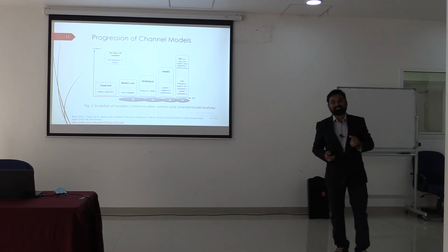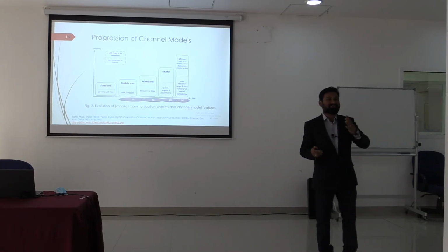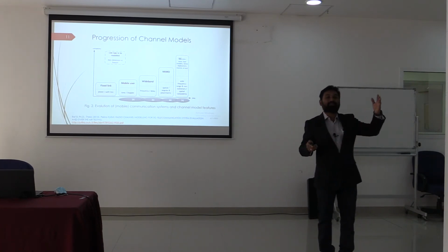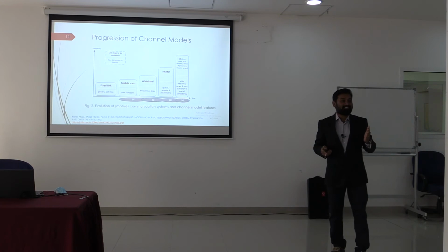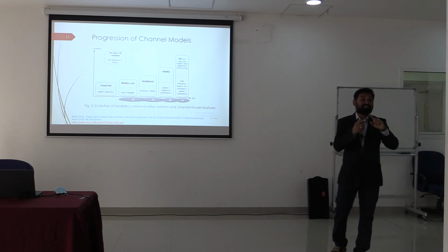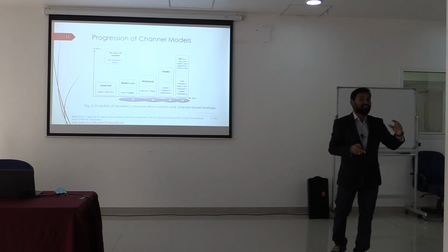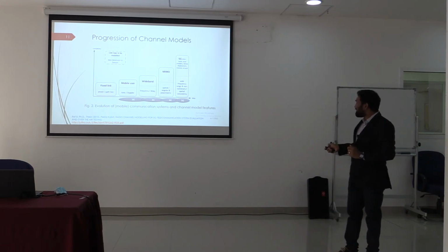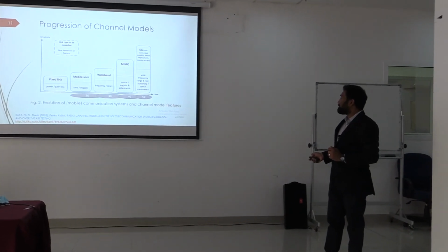What is spatial consistency? For example, I am going to implement 4x4 MIMO in the base station. Base station space is not a problem. You can implement around 32x32 antennas, 64x64 antennas. But take your user equipment. Where is the space to provide uncorrelated paths within the small mobile equipment? Or your tab or laptop, is it possible to provide it, given certain limitations with respect to the spatial correlation? Then how do you maintain the correlation parameters to obtain the bandwidth? So these are some of the limitations when we are modeling the channels, and what are the features we are going to incorporate.